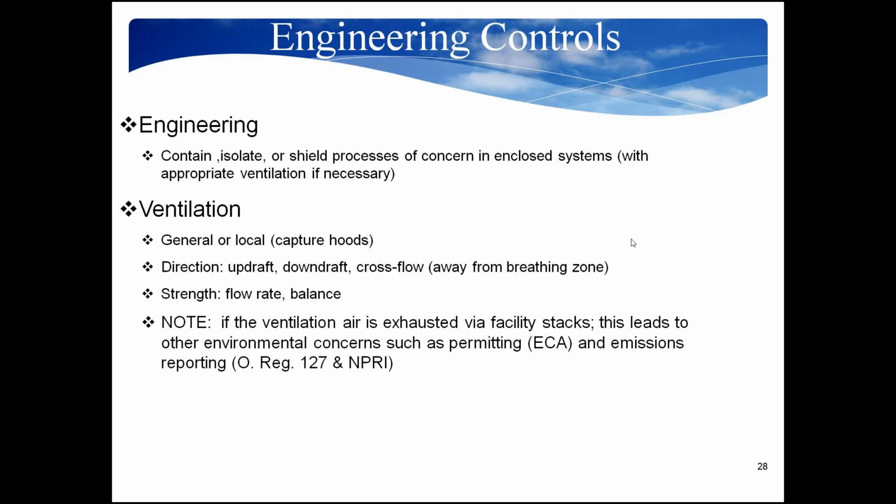You have to consider the direction of the ventilation. Is it an updraft ventilation or downdraft or cross flow? You would consider all of these and just ensure that it's away from the breathing zone. The last thing you want to do is bring the contaminant from its source across the person's breathing zone, so you're actually exposing them further to contaminants.